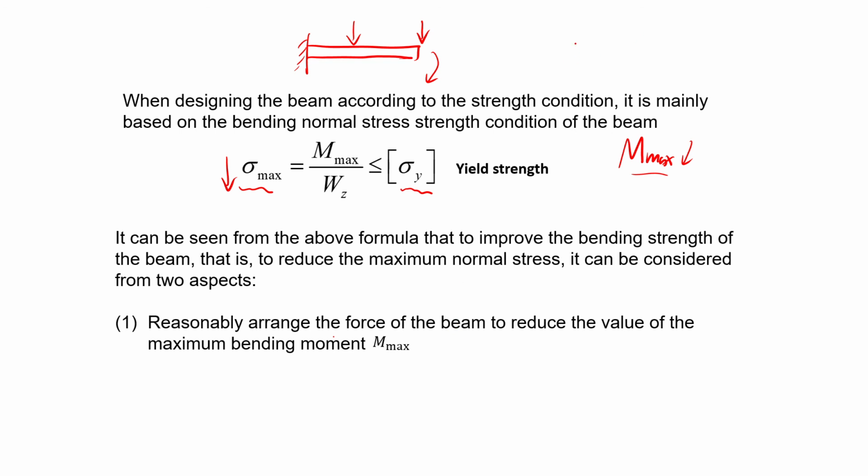When you design a bridge, you need to be careful. For example, if you have a bridge where at the beginning you only have 2 supports, and you apply a loading here, the deflection is very high, because the moment at the center point is very high. To reduce that moment, you can put a support in the middle, right? That's why in bridges we have multiple supports.